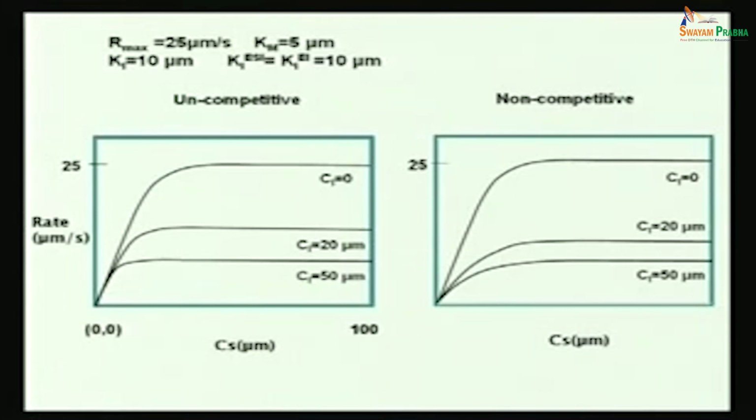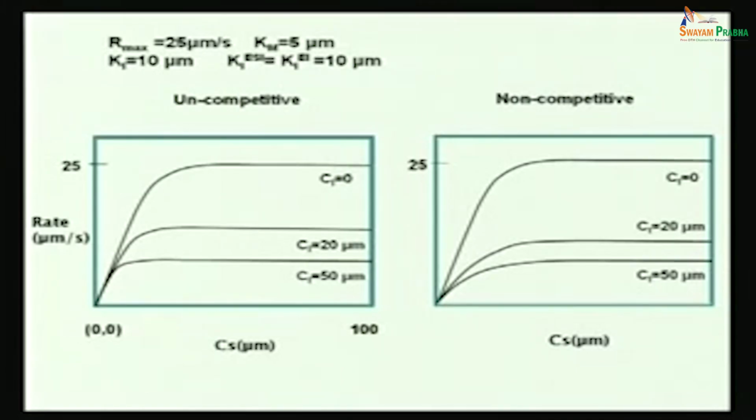So, if the product itself inhibits the reaction and you do not want inhibition, for example, what would you do? Very straightforward answer. What would you do if the product is inhibiting the reaction and you do not want the inhibition to happen? Constantly take out the product, yes, that's the right answer, but there's a problem. If you have a big reactor, a CSTR essentially, what is large in a large CSTR?